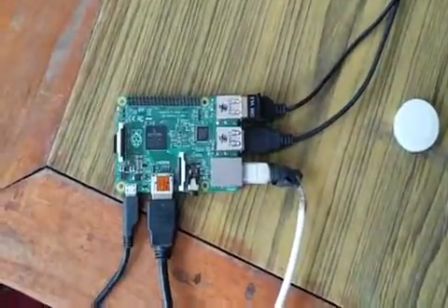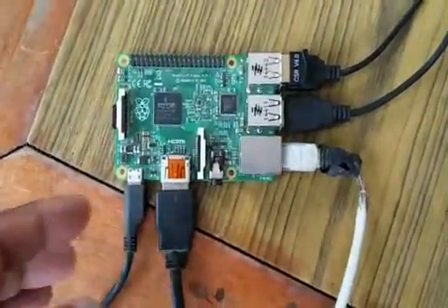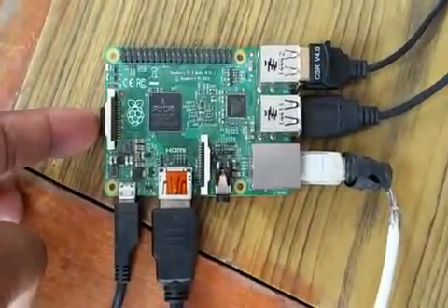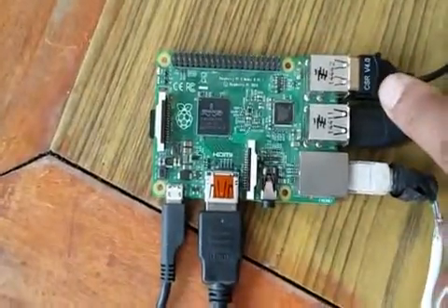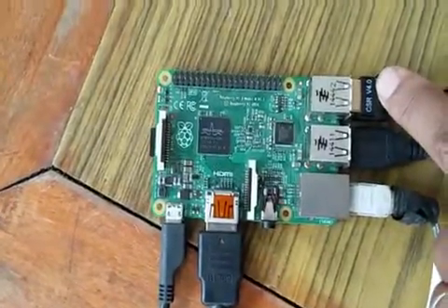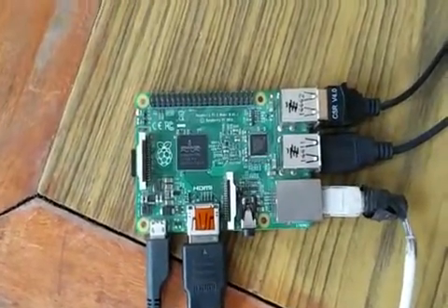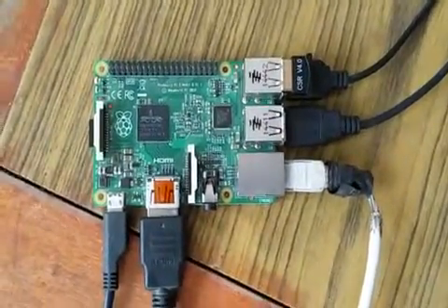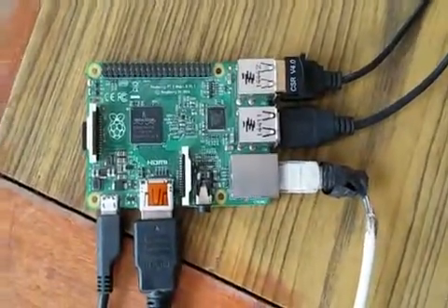For our modern cowbell problem, we are using a Raspberry Pi as the base computing engine. This is Raspberry Pi 2, which has already been loaded with a micro SD card and has Raspbian on it. We have also put in the Bluetooth USB dongle, which is version 4.0. This is absolutely required because the proximity beacons normally use the LE mode of the Bluetooth, and if that is not present in the Bluetooth USB dongle, beacons will not be recognized by the Raspberry Pi.